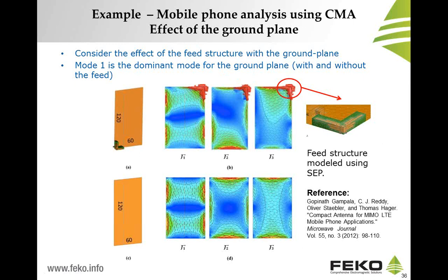So our characteristic mode analysis solver can solve problems that also include dielectrics, that are modeled using the surface equivalence principle. If you would like to gain a little bit more information on this feed structure, I refer to this reference over here that was published in the Microwave Journal. Now, to get back to the point here, we solved this model with the feed, with characteristic mode analysis, and obtained the first 3 modes.